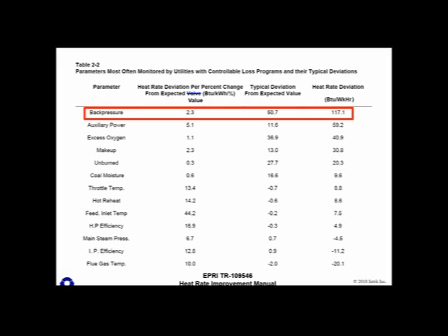But they kept the unit running, and they temporarily patched the joint while online and kept generating electricity. And the owners of the condenser at this plant placed a very high priority on keeping air in-leakage low. If they had not kept it low prior to the event, then it's very likely that the air in-leakage from the expansion joint would have tripped the turbine exhaust pressure limit and taken the plant offline.